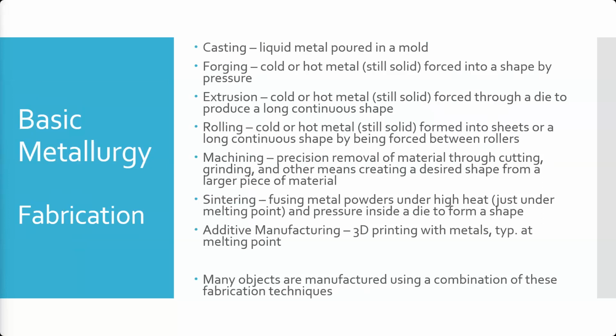It's different from extrusion in that you're going through a roller, whereas extrusion, you're just forcing it through a fixed shape die, not a set of rollers. They do a similar thing. They both cause the metal, forging, extrusion, rolling, all force the metal to flow, a still solid metal to flow. They create very, very strong parts. Casting, the metal is not quite as strong, okay? But it's a lot easier to do, okay? Liquid metal flows better than solid metal. It takes less pressure. You don't have any pressure involved.